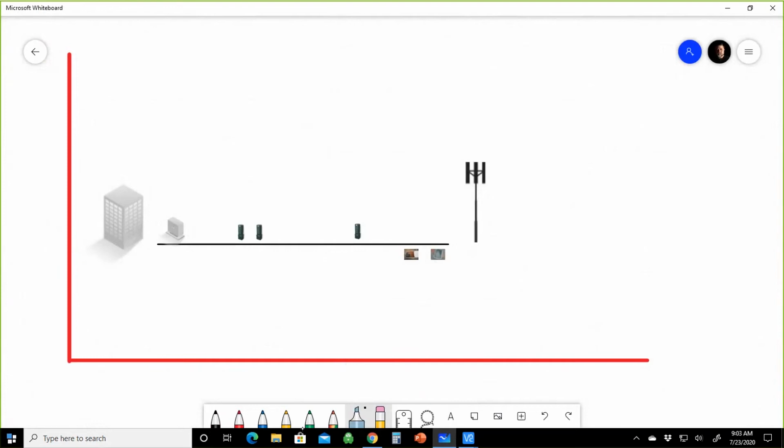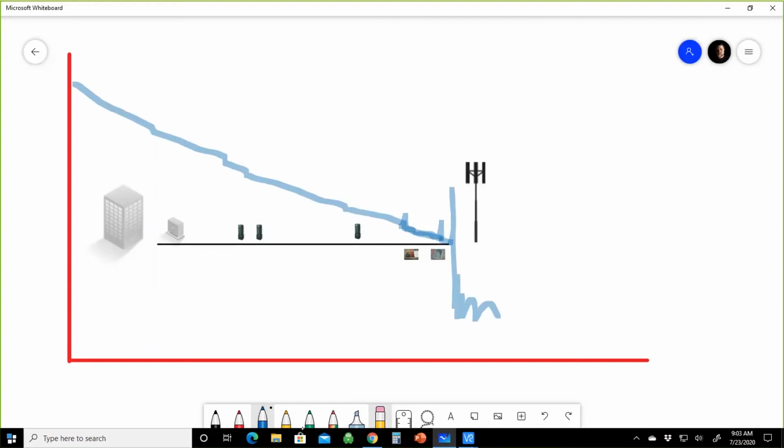So essentially, what we're going to have is our launch, then the vault, splice, splice, splice, splice, splice. Actually, connectors. These two are connectors. This one's a connector, and this one's probably a connector. And then, you know, we have our end, whatever, right? So this is what we're looking at on a standard trace here. And let's say that this was shot at 10 nanoseconds. 10 nanoseconds is a very short pulse width.